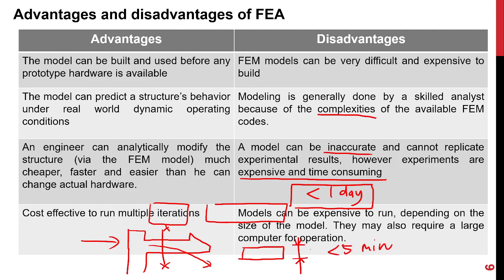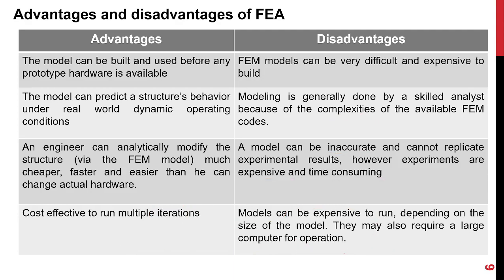What do you want to say? Do you put 5mm thickness? Do you put 10mm thickness? Which one will have a proper deflection? When it goes in, it has to deflect. Maybe it has a deflection of 3mm. So under 3mm deflection, is there any stress at the problematic area, the sharp corner? Design engineers encounter things like this every single day. You may need to do 4-5 analyses when you design. So make sure your design is not too overly complicated.